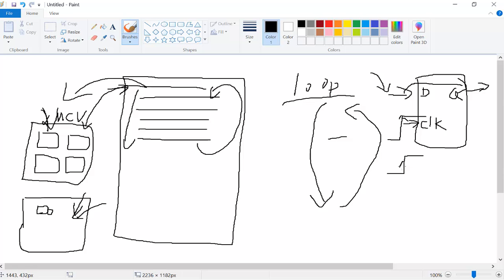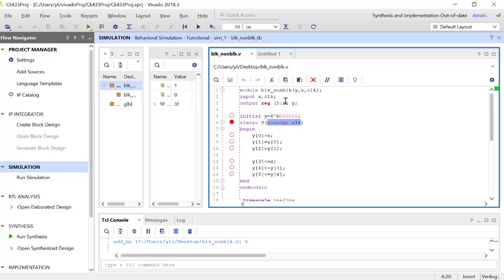If you haven't taken digital electronics, we're going to design D flip-flops there, how to design the rising edge triggered D flip-flop. But just remember this device can only update the output, which is called Q, at the rising edge. Can you design a D flip-flop that only senses the negative edge, the falling edge? You have to modify the circuit. It's doable, we have been doing this a lot, but usually you don't do it.